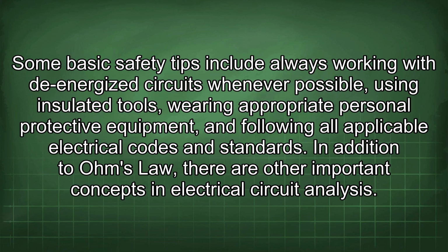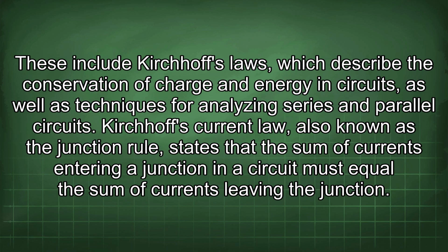In addition to Ohm's law, there are other important concepts in electrical circuit analysis. These include Kirchhoff's laws, which describe the conservation of charge and energy in circuits, as well as techniques for analyzing series and parallel circuits. Kirchhoff's current law, also known as the junction rule, states that the sum of currents entering a junction in a circuit must equal the sum of currents leaving the junction.